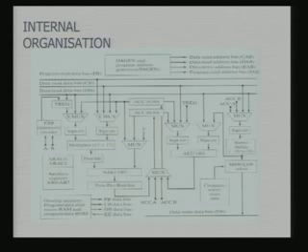So this gives you a diagram, an internal organization, and you will find the complexity in the data path which is there. It has got two accumulators, and let us look at this part where you have got this multiplier. So, you have got this 17x17 multiplier, and this multiplier on its path itself has got an adder.